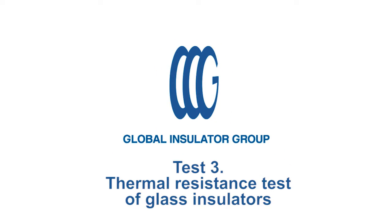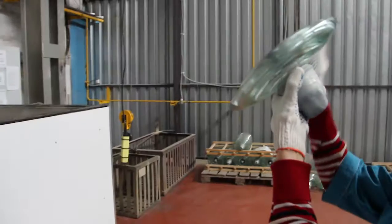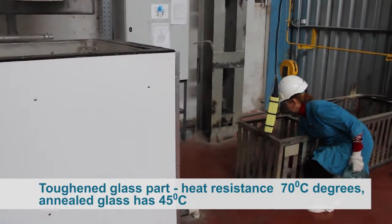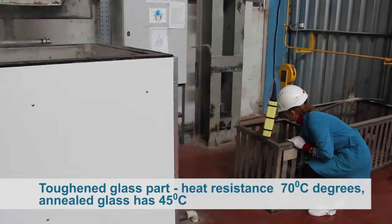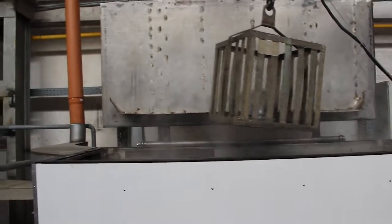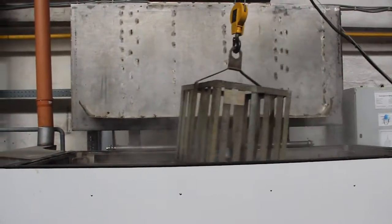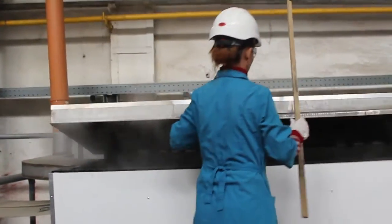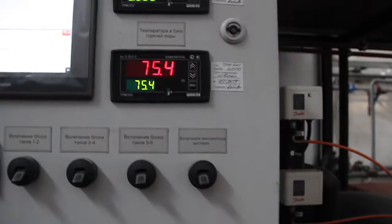Thermal resistance test. High thermal resistance of toughened glass, 70 degrees centigrade. The annealed glass withstands only 45 degrees centigrade. Toughened glass part guarantees correct operation of insulators within the temperatures range from -60 degrees to +50 degrees and at